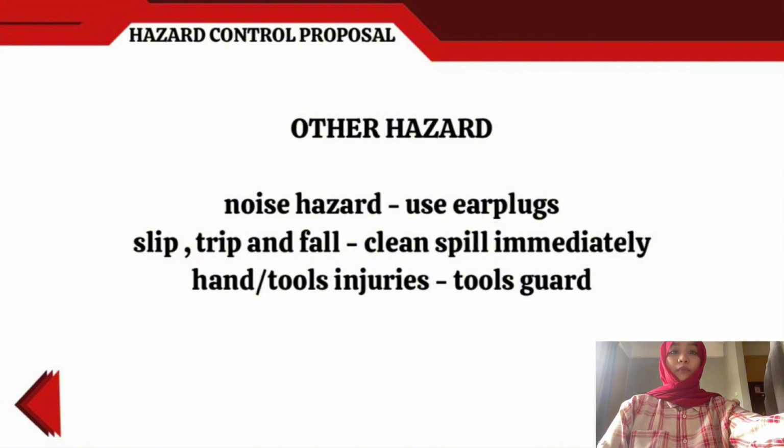Besides those, we also found other hazards. Noise hazard can be controlled by using earplugs. To prevent slip, trip, and fall, spills must be cleaned immediately. For hand or tool-related injuries, tool guards should be installed. By following these controls, we can minimize risk in the workplace.